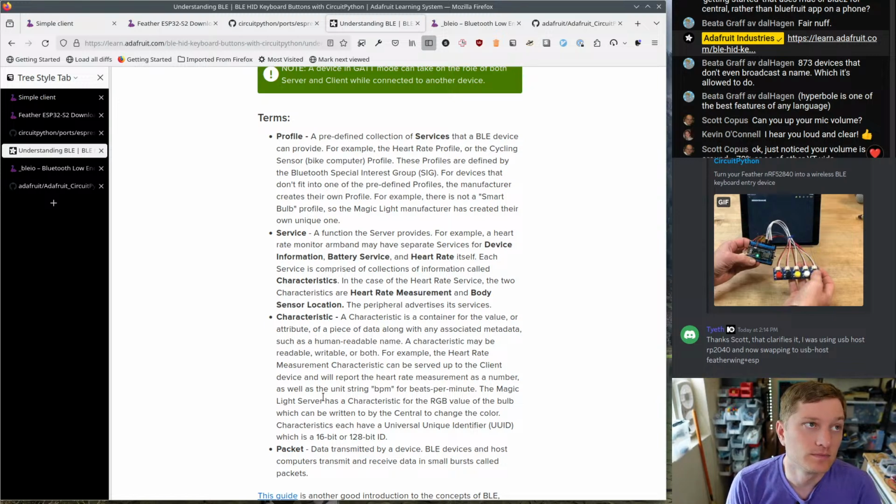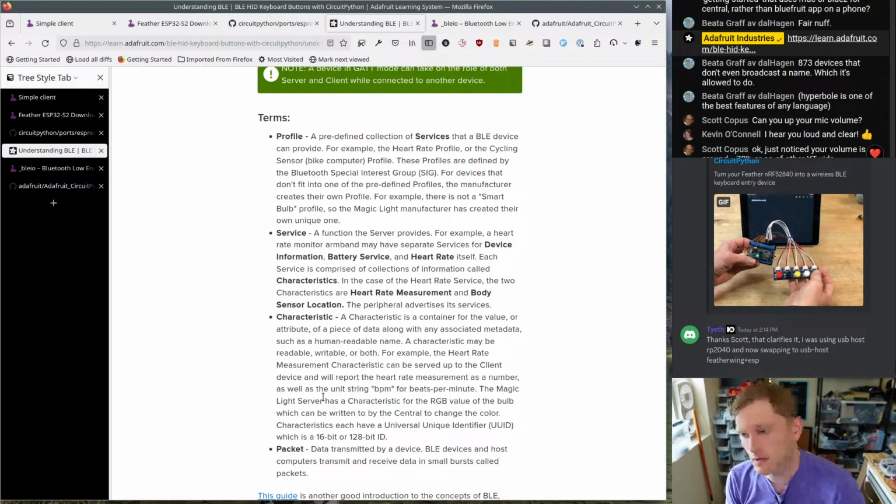So we could connect to other servers, to services on the other device that we're talking to. But for a long time, the Bluetooth stack that the ESP had expected you to say what services you wanted to serve before you did the GAP connection process, which is fine if you're a fixed device where you're just the temperature sensor and you don't care who's connected or what's running. You're always just going to be a temperature sensor. You can compile it straight in.